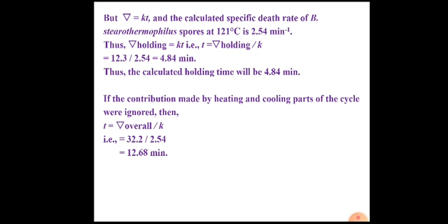This unnecessary exposure is beyond the time required for killing, which leads to degradation of nutrients, which leads to decrease in the quality of medium. Therefore, it is very essential to consider the contributions of del heating and del cooling. So this is how the design of batch sterilization is done, considering heating period, holding period, and cooling down periods.